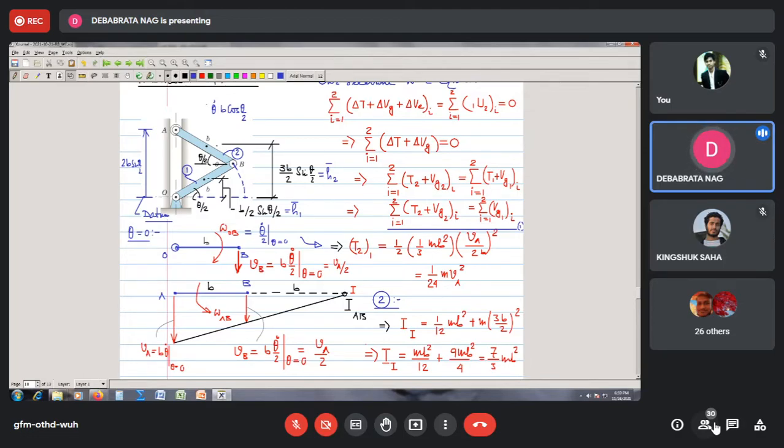I hope I have explained the solution methodology for this problem. In this one problem you see there are three features. When you have a system of rigid bodies, how do you calculate, particularly if some link is in general plane motion, how to calculate its kinetic energy, then you need to do kinematic analysis member by member, and you have several approaches for it. You can follow the absolute motion analysis method, the relative velocity method, or the instantaneous center method.